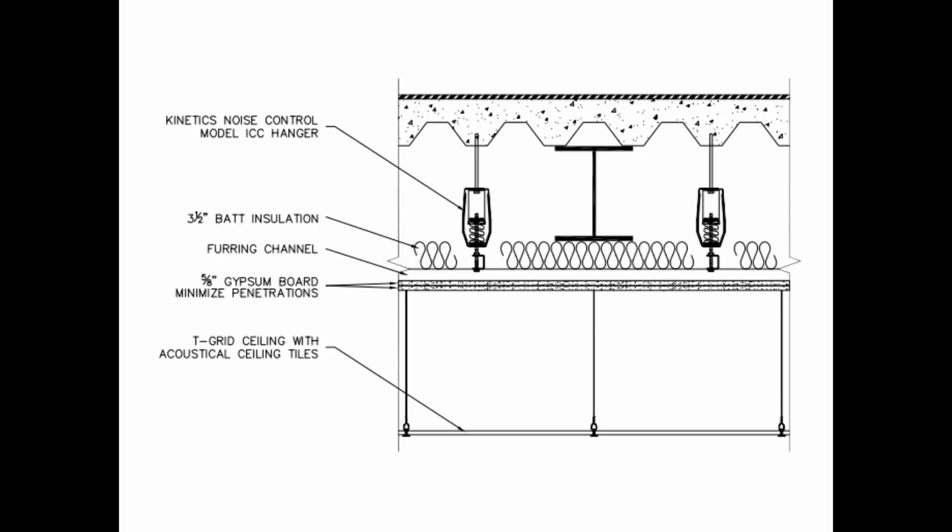The ceiling, we would hang a sound isolation ceiling, a couple layers of gypsum board on spring and neoprene hangers, and then we wanted an acoustical ceiling. So like a T-grid ceiling is good because in one square you can put sound absorption, in another square you can put diffusion.